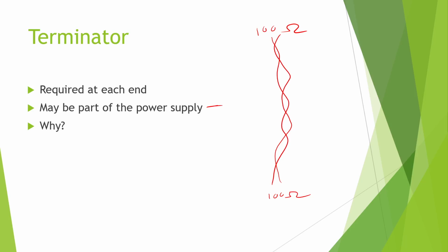All right, the simplest way, well, what you could do is unhook a resistor, check out one, plug it back in, go find the other one, or check the power supply, see if it has one, right? The other option is you could just test the wires. You can just go probe with my voltmeter in ohm mode. All right, now, if we're doing that, what resistance should we see?